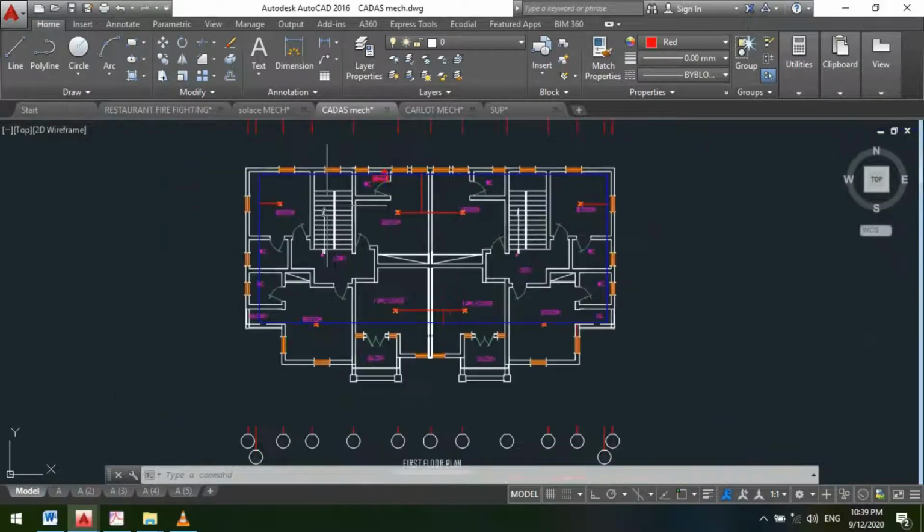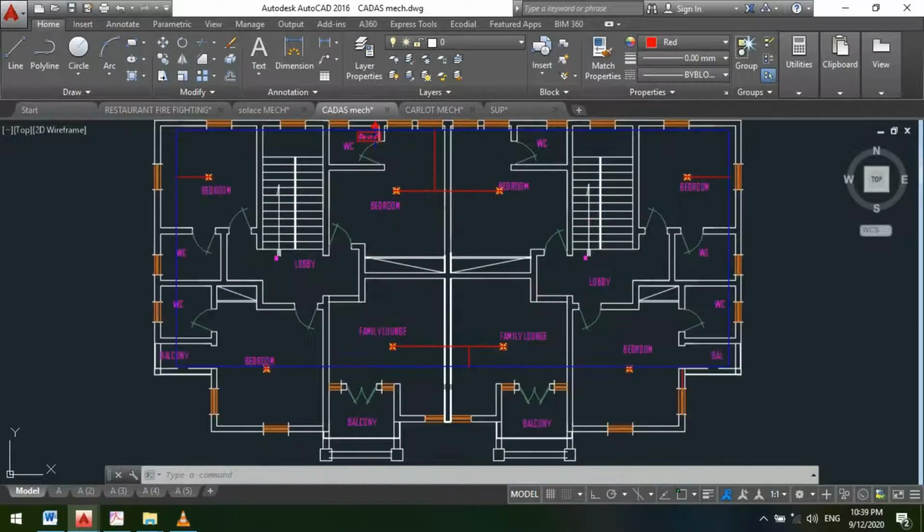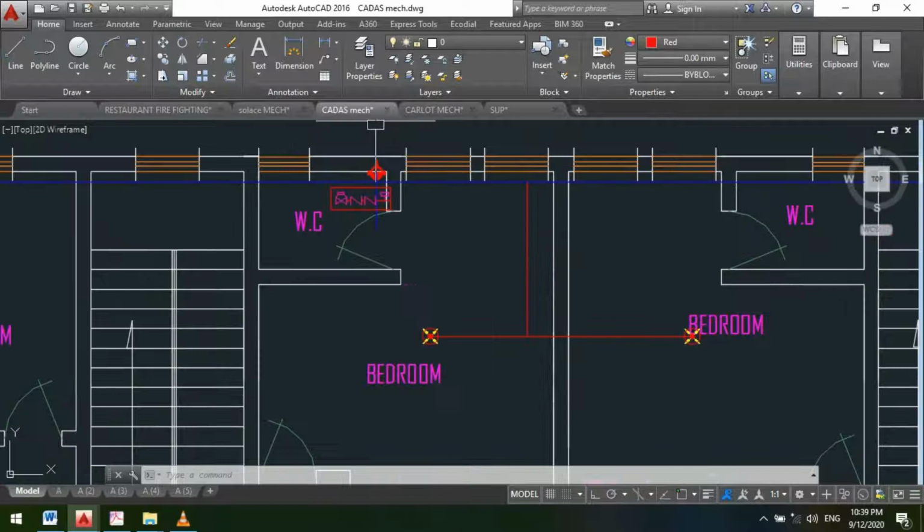For example, if our dimension is probably 49 by 49, which is roughly 2,400 square meters, we'll have to divide our building into zones, where we have a zone here and another zone here. So this is how we create zone control assemblies for our buildings, although you can still read NFPA 13 for further elaborations.